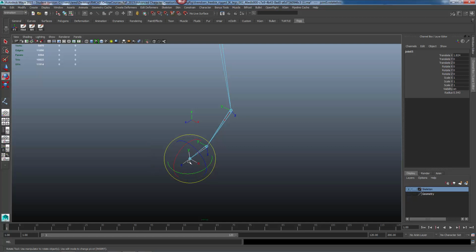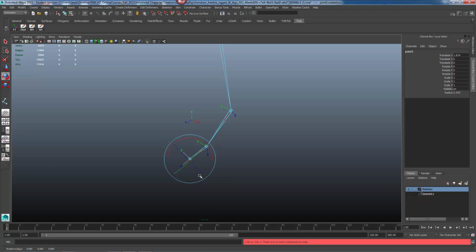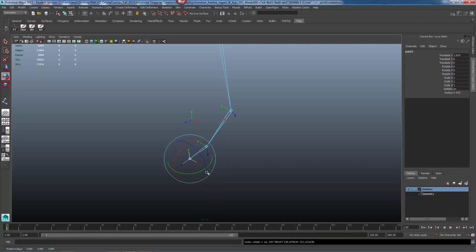We're going to rotate this thing to point at a fictitious child out here. So if there was another joint out here, basically, I'll hold down the J key to use the snapping function and just click and drag this. And I'm stuck in this weird transformation, so I must not have grabbed the handle very nicely. So hold down J, click on this handle and drag, and you're seeing that it's snapping now. And that's the desired effect. Okay, so this is pointing to a fictitious child out that way, which is pretty good.